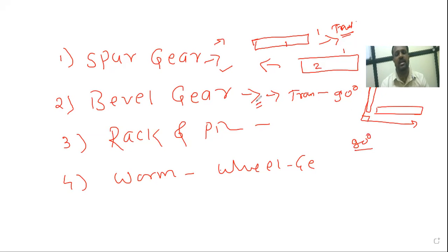Then what is the practical application of the bevel gear? Anybody here? We have seen the bevel gear. Its practical application is that it is generally used in the differential gearbox in the automobile. Here we have to use the differential gearbox, the rear axle differential gearbox.